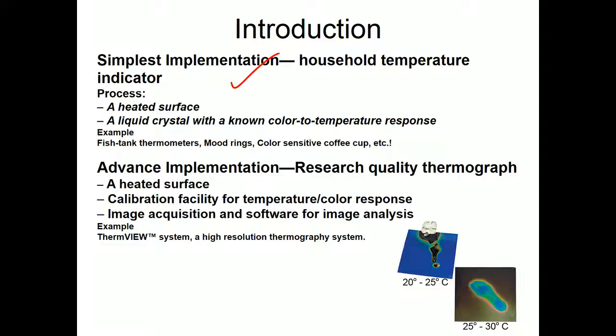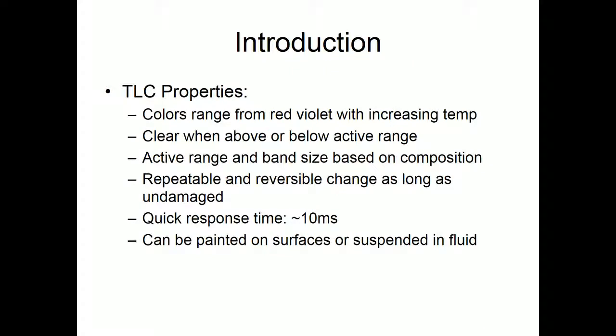thermography, that means which you are going to use to calculate the temperature, as in the case of your Nusselt number, you need a heated surface, you need a calibration, because the color and the temperature calibration has to be done, because you know the color that is coming out and you know the temperature. So, a priori you need to have a calibration done. And you of course need image acquisition and other software, and you need high resolution thermography images basically to visualize and make out what these colors are actually telling you.